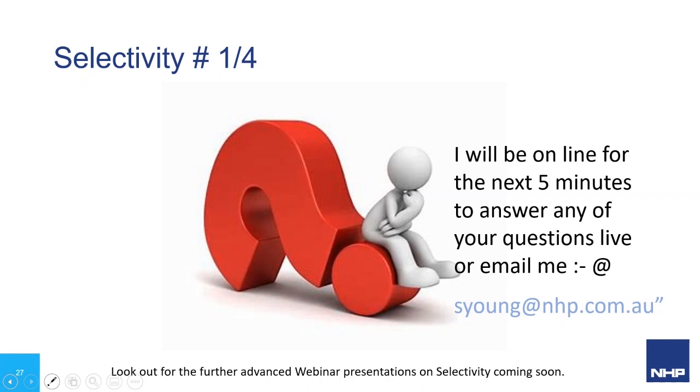Thanks for that. We have another one. This one comes from Charville. He's asked the question, if my distribution board fault current is rated at 14 kA and I have used a 15 kA circuit breaker as the main breaker, can I then use 10 kA breakers downstream at that distribution board? If the fault current goes above 15 kA, will the main upstream 15 kA breaker protect the other 10 kA breaker?